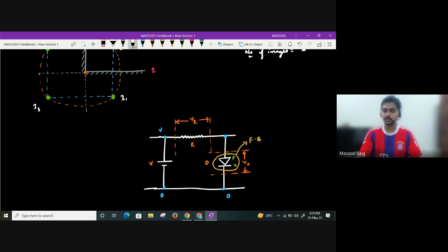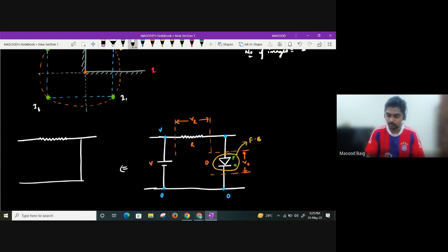And it is given that it is an ideal diode. So because it is an ideal diode, in forward bias, the ideal diode will offer 0 resistance. So you are going to get something in this manner. Now this is going to behave as a closed circuit. So this is our V value, this is our R value. As you can see, across the diode there is no potential difference at all, right? So whatever potential difference is there will appear across the resistor, and across the diode the potential difference will be 0. Across the resistor, it will be V. Clear?